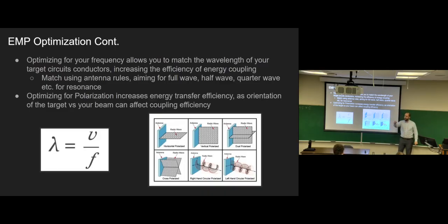Yeah. Do we have to sacrifice some of the energy to make it be spread around like that instead of staying in one single polarization? So luckily for polarization, you don't have to sacrifice energy. It's not like frequency where you do have to spread it, because each frequency is a separate signal. Polarization is inherent to a signal, but it is expensive. Polarization is imparted by the antenna. So you design your antenna to have a specific type of polarization.